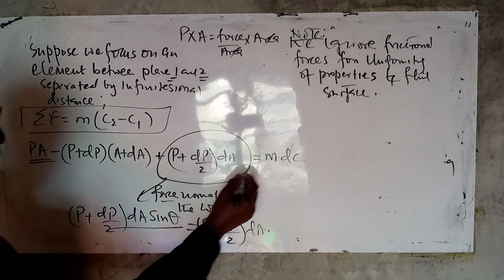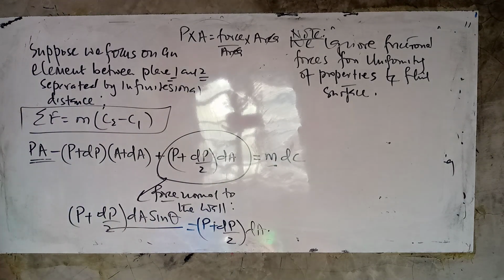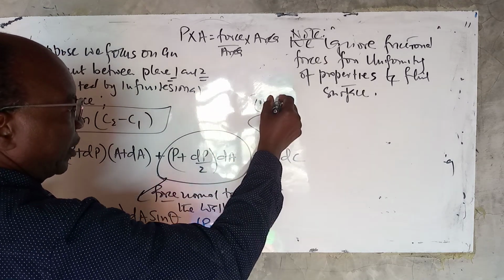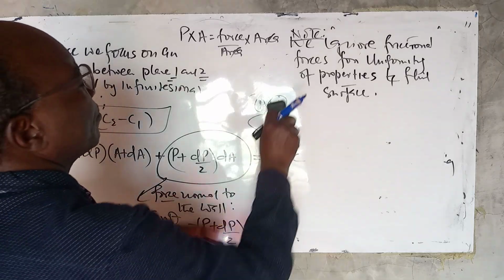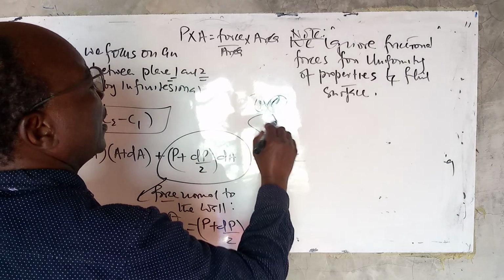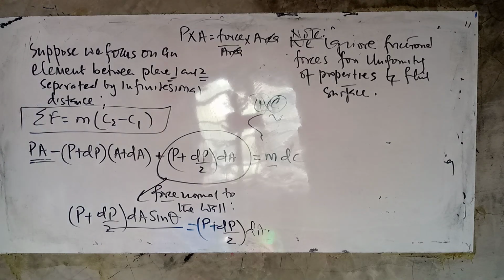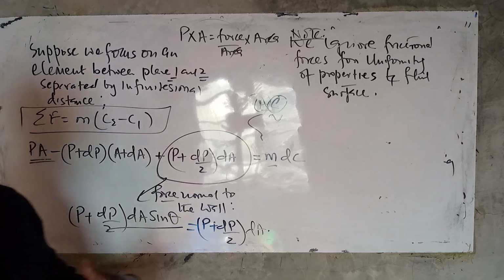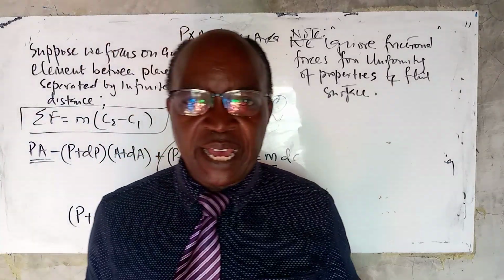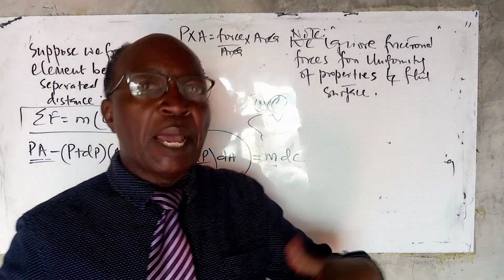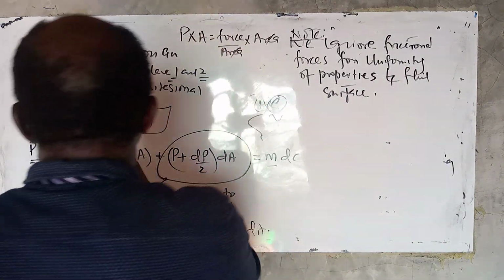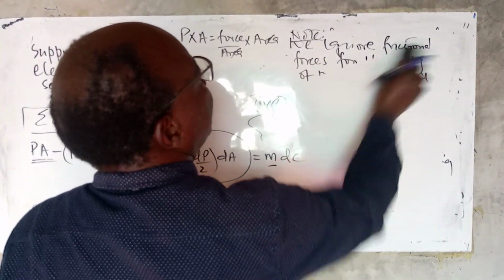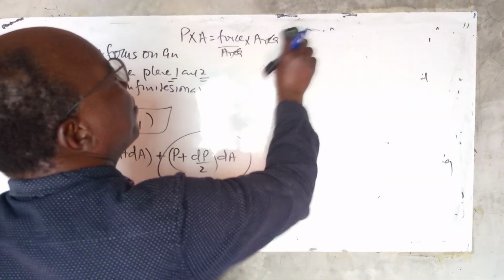And don't forget, m from the continuity equation is AC over v, where A is the cross-sectional area, C is velocity, and v is specific volume. And so if we open up this expression and ignore the second order components, or what we call the doubly infinitesimal components, let's open up this expression now.